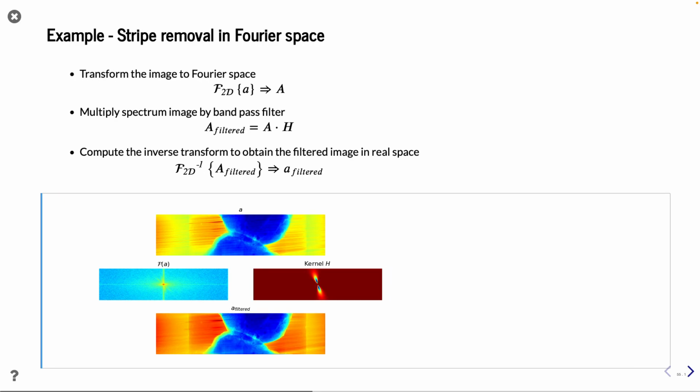So, how can that be used? In this case, I designed a matched filter for some structures. We did some experiments, and unfortunately, the normalization wasn't successful because the background was changing shape all the time. So we got these stripes in our background field, and they were quite annoying. We wanted to get rid of them, and the approach was to look first at the Fourier spectrum and identify that these stripes should be something a little bit tilted along this line.